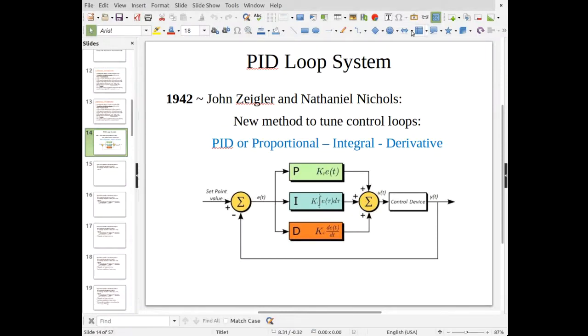As I was saying before, hopefully you caught all that, if we are going to do just proportional control here, then we're pretty much guaranteed that we're going to have steady state error. The only way to get rid of steady state error with nothing but proportional control would be to drive your gain so high that in reality it wouldn't be able to do the job anyhow. So you're always going to have some steady state error if you just do proportional control.